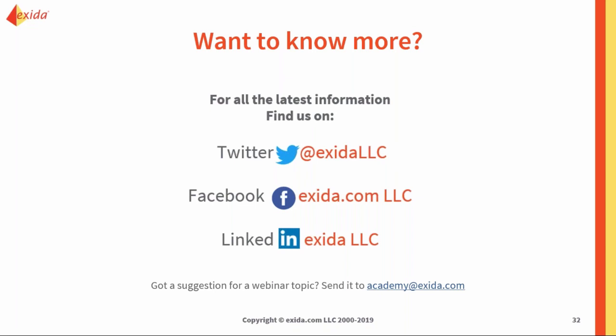Okay, if a device has a systematic capability of SIL 3, but a PFD average gives you SIL 2, what's the overall SIL? This is a great question. Your overall SIL is whatever that least factor is, or the lowest common denominator. So if you have those 3 barriers or those 3 hurdles, and each one gives you a SIL 3 except for one of them, maybe that PFD average gives you a SIL 2, that's your limiting factor. Your entire SIL is going to be that SIL 2. So whatever the lowest one, no matter what barrier it is, that is going to be your limiting factor.